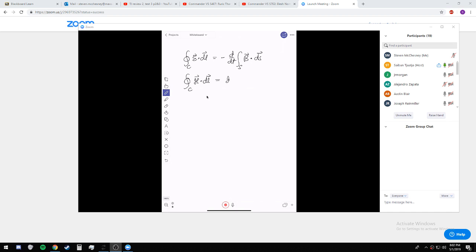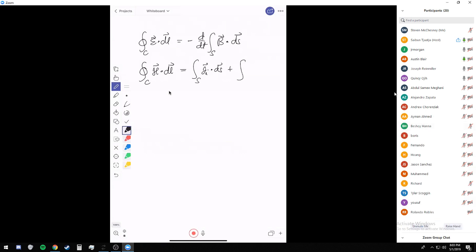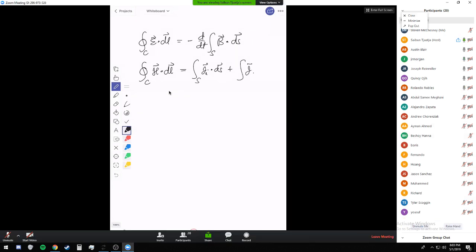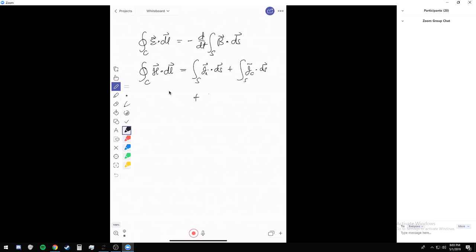So we have this J, oops, it's not quite right. It's basically integrating over the surface. We have the impressed current dot ds, I just skip the argument here, plus the conduction current dot with ds, plus d dt integral over the surface, the electric flux density dot ds.